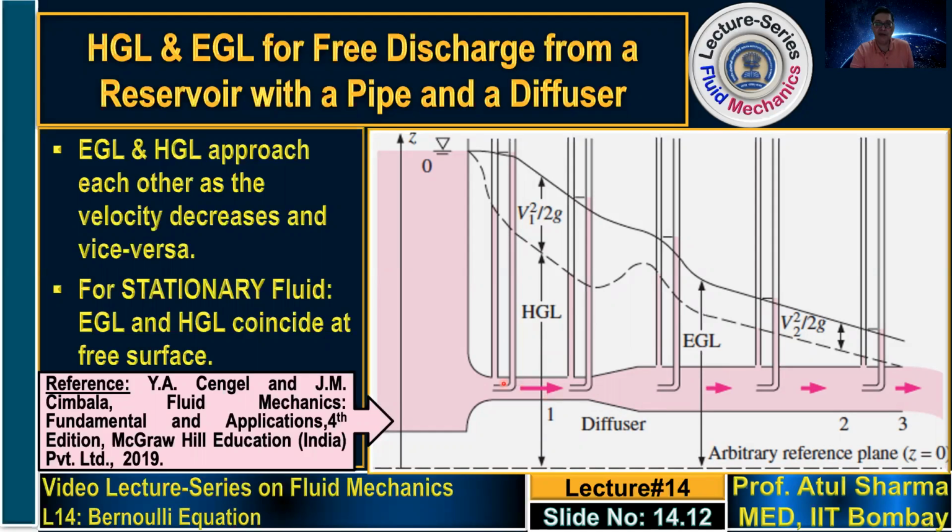So in this case, even when the fluid is passing through a pipe of constant cross-sectional area, you will see what is shown here: this solid line corresponds to the energy grade line, and this dashed line corresponds to the hydraulic grade line. Now, what you see here is even when it is passing through this constant smaller pipe diameter or a larger pipe diameter, in this region also the total energy grade line is shown with a downward slope. Here also there is a downward slope. Now, as you can see, the slope is constant.